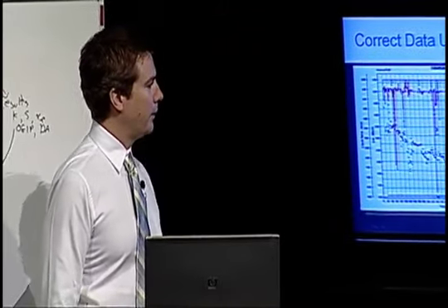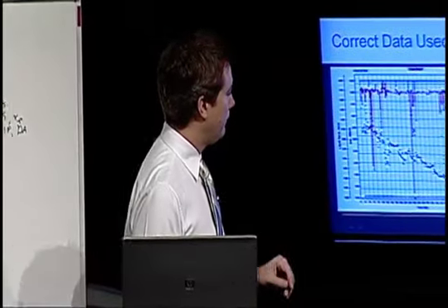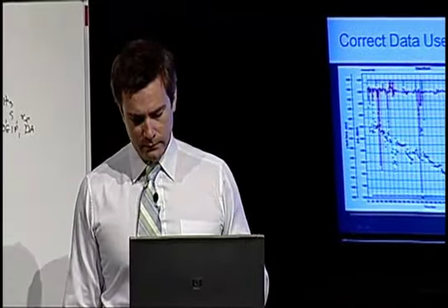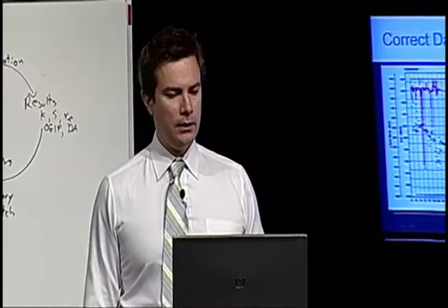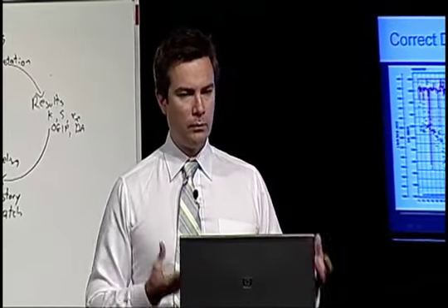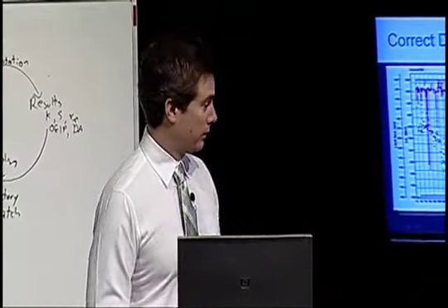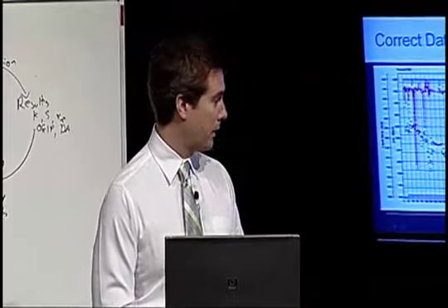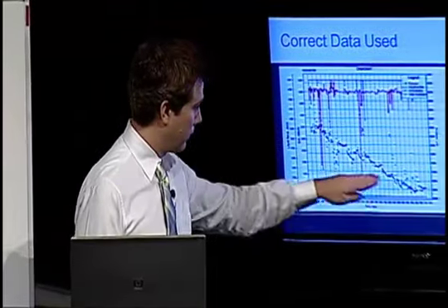When the correct data were used in this case, as I found out later on, we had access to the tubing head pressures, but the field personnel didn't know what it was that we were looking for. So they sent the data, I suppose, that was easiest to get access to, or the data that they thought that we wanted, which was the meter run data. What I actually wanted were the tubing head pressures.